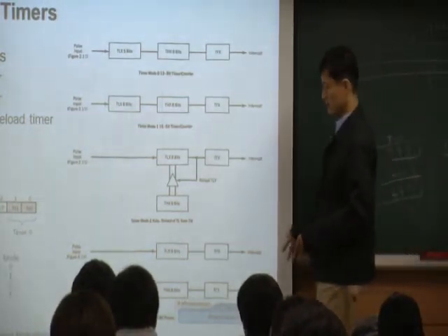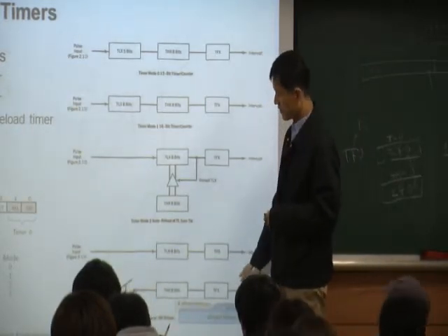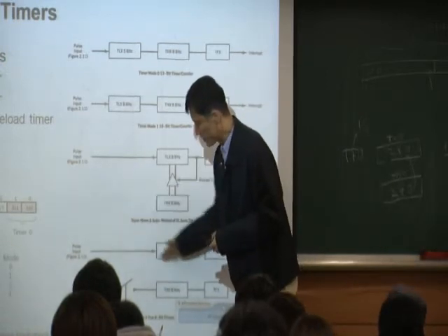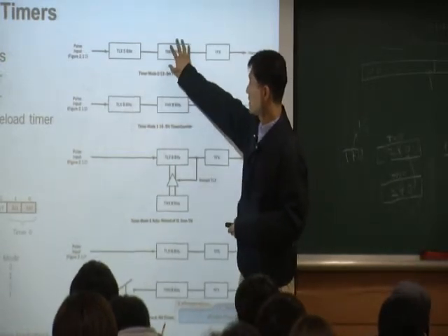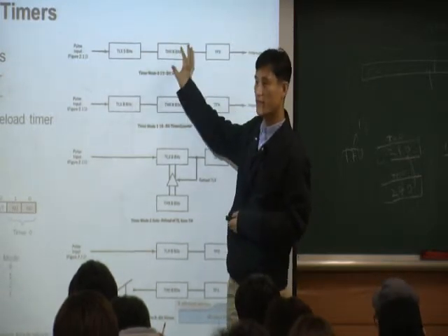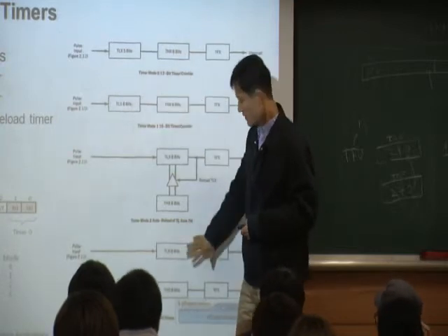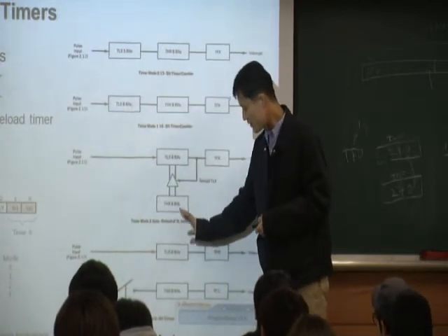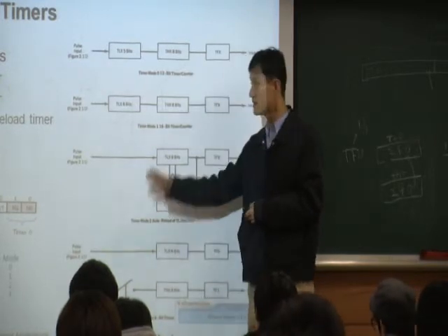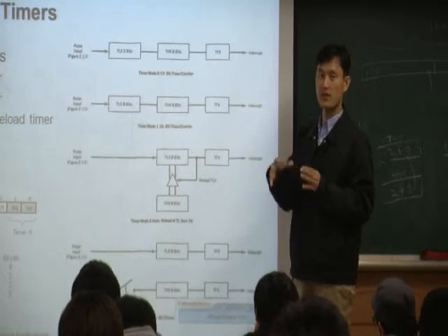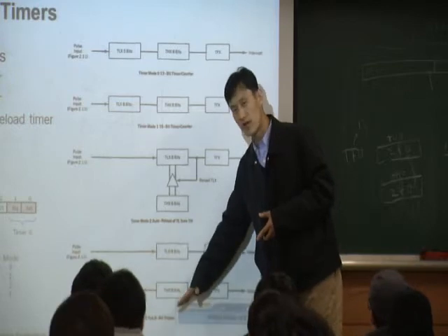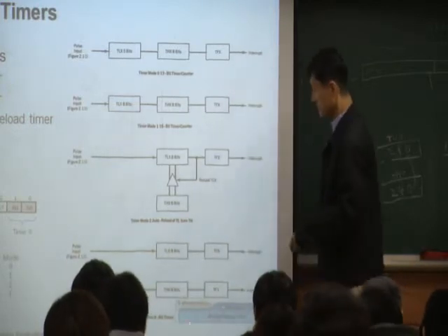The last one is not popular. We don't use it much. But this one actually uses two different timers. Since we have TL0 8-bit and TH0 8-bit, we have two different 8-bit registers. We are going to separate TL0 and TH0 and make two different timers. This is all about timer 0, hardware timer 0. So inside the one hardware timer, you are actually making two timers. That's what it is, but this is not that popular.